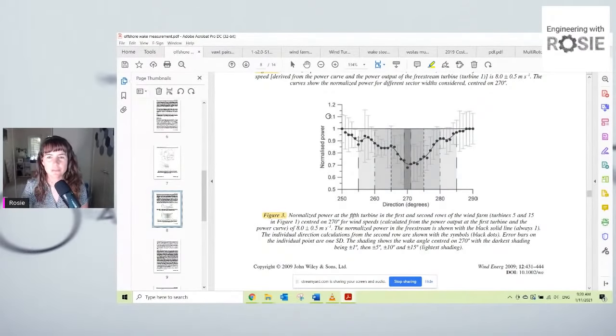And then there is one other issue aside from the loss of power. You also see increased turbulence in all of the downstream wind turbines that are in these wakes, and that can have a negative impact on the lifetime of the turbines, because you get these turbulent loads which vary a lot, and that's quite a harsh operating environment.